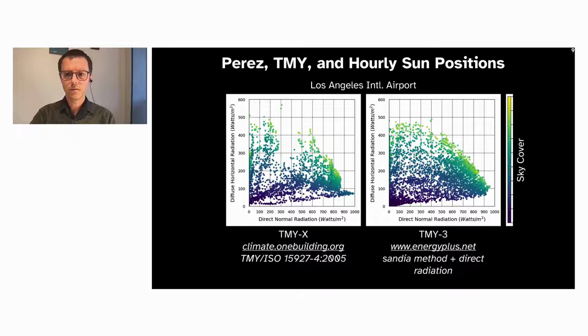These measurements include values like temperature and wind that do not directly impact light. We don't actually know which of these weightings is better at generating realistic distributions of interior lighting conditions, but the TMY3 method does more heavily weight the key parameters for daylight. Unfortunately, this data set is only available for the United States, and in the case of comparisons of performance across sites, such as performance standard simulations, a consistent selection procedure is probably more important than individually being more like reality. So there are trade-offs either way.